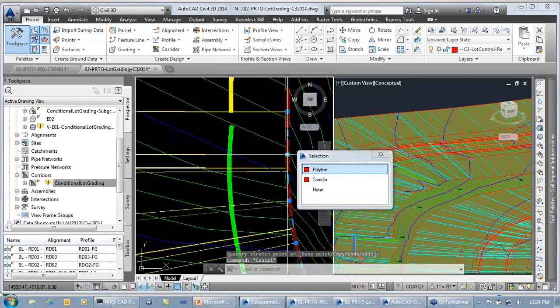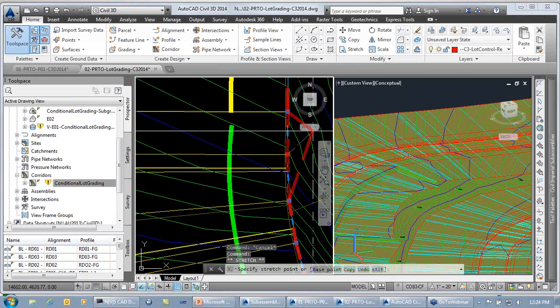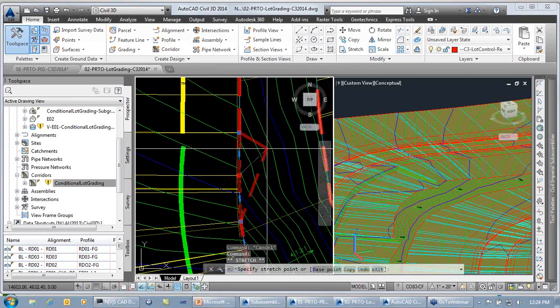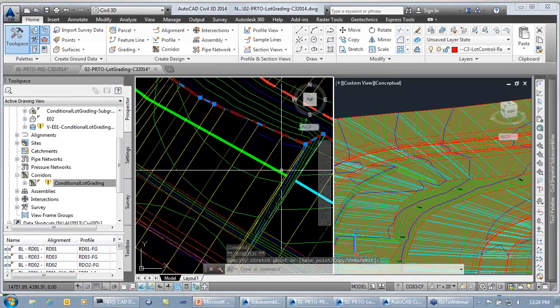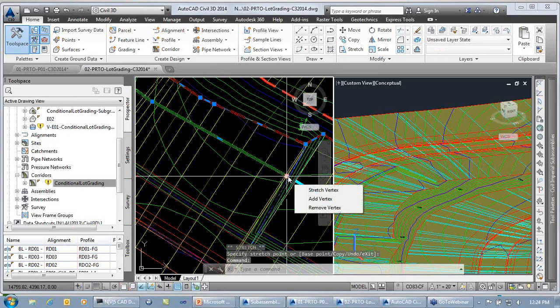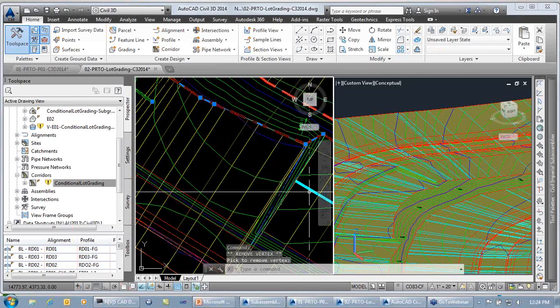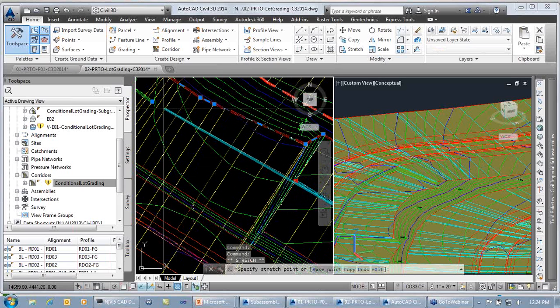And what I'll do is I'll come in and maybe pull this in and do that same bump out here to see if I can get the contours to wrap a lot nicer. And then maybe I'll do the same thing on this end as well. So I'll come in and say, well, let's get rid of that vertex. And then we'll pull our walkout lots a little bit further here.